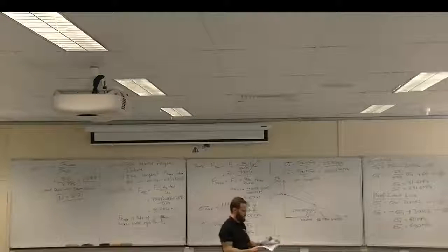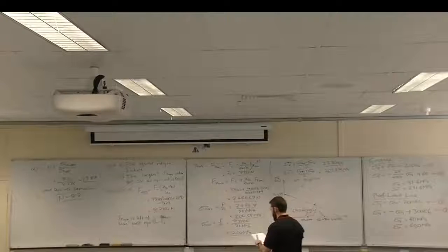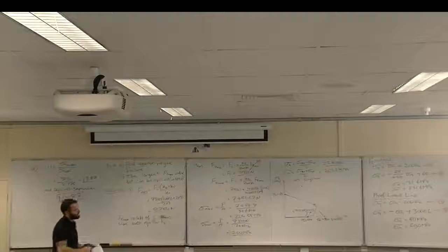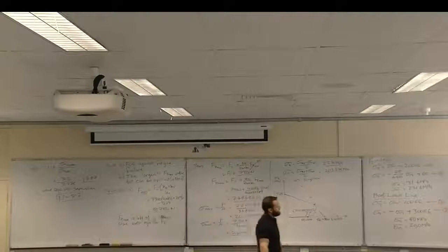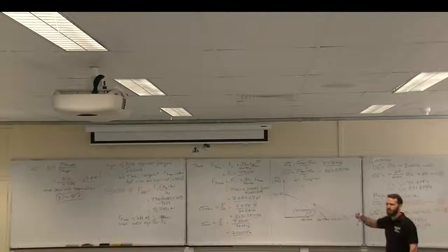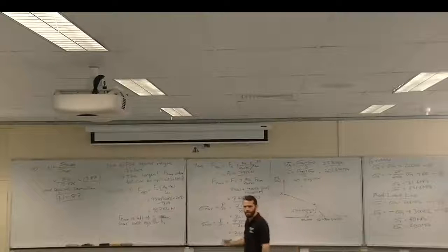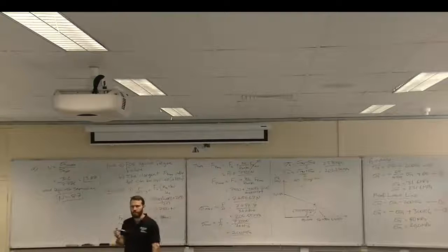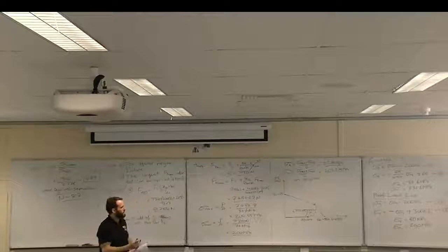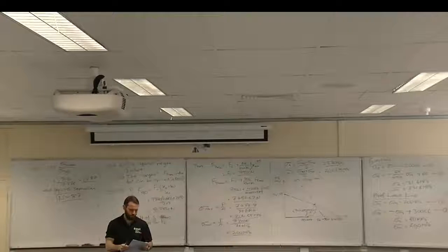Alright, now the last thing was B, what was your allowable force. It'll be in the notes so I won't write it up, but sigma A and sigma m, if we add them together we get sigma max. And that sigma max is just equal to force max divided by the area of the bolt. So bring the area of the bolt back, and that'll calculate your maximum force, or your maximum stress theoretically.